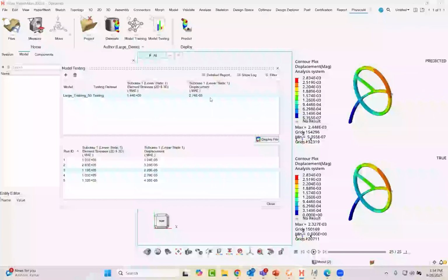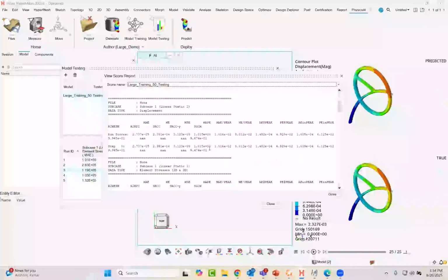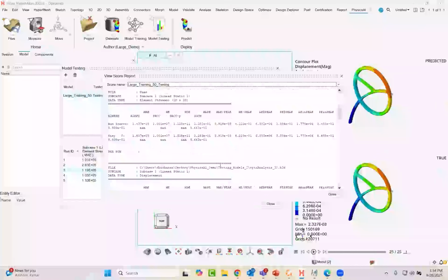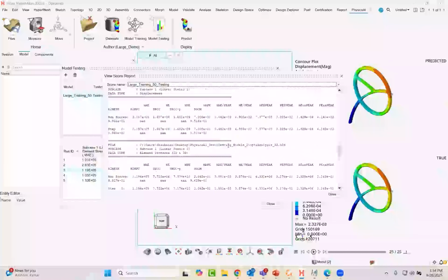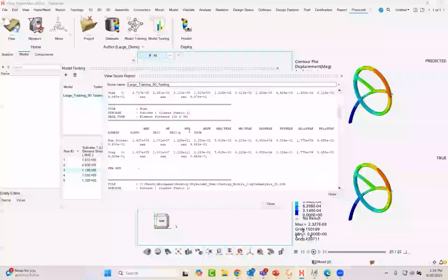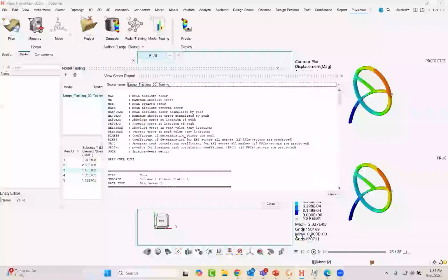The other thing you can do, like I already mentioned, if you want something even more substantial than looking at the MAE, is go to the detailed report. There are a number of other statistical measures for both displacement and element stresses. Again, this just gives you confidence that the predictive model you've generated is an accurate model. It's pretty cool that you have these values available at your disposal. Most engineers, and myself since I started utilizing this, use MAE, which is the mean absolute error. But you can see all of these broken down in terms of what they are, MSE, mean squared error, etc.